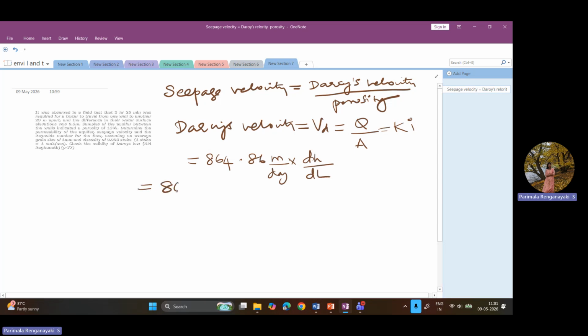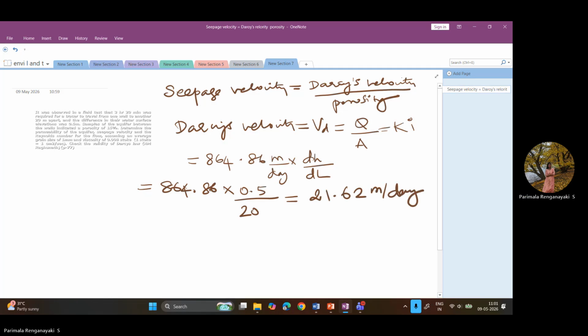So 864.86 into 0.5 divided by 20, which is equal to 21.62 meter per day. So we got our Darcy velocity.